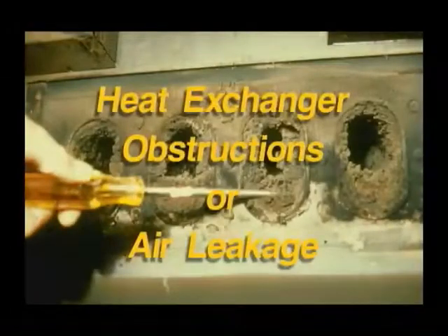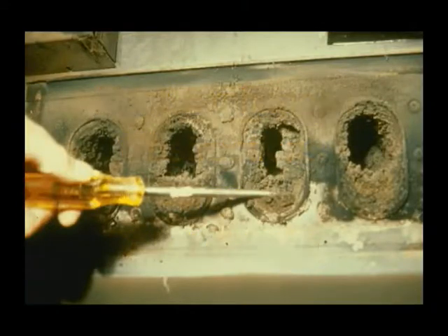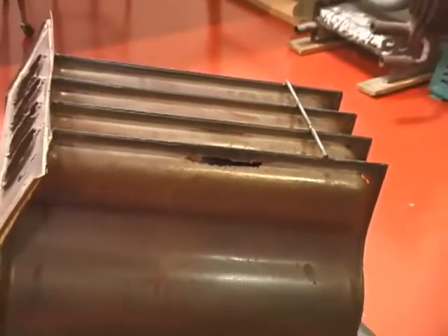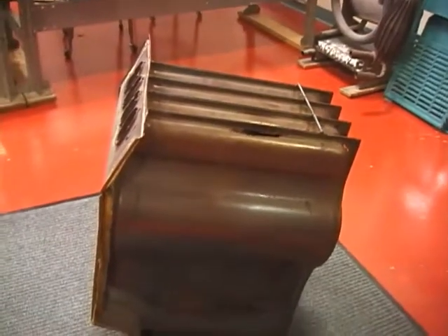Heat exchanger obstructions or air leakage. A very dirty heat exchanger will hinder or stop the flow of combustion gases out of the appliance. Leaky or cracked furnace heat exchangers can either depressurize or pressurize the vent system, causing draft problems as well as incomplete combustion.